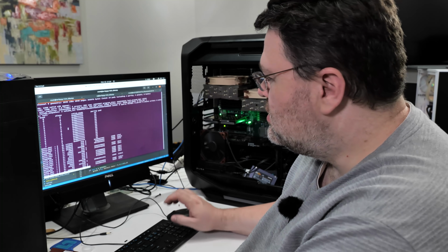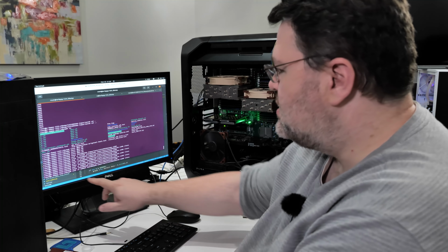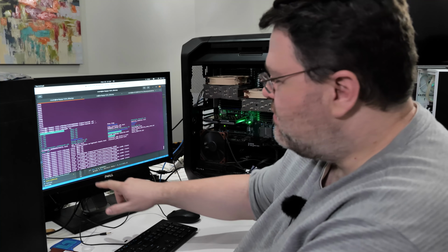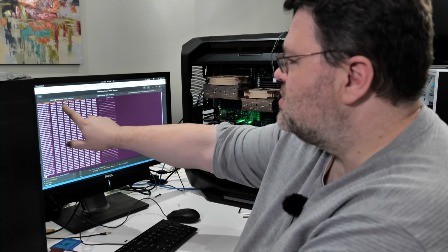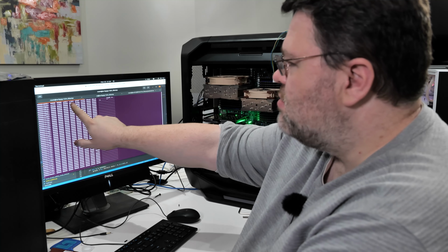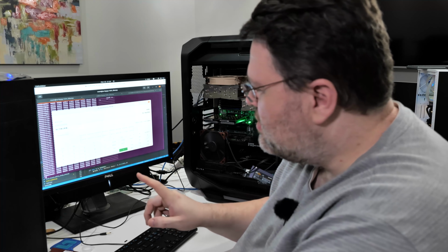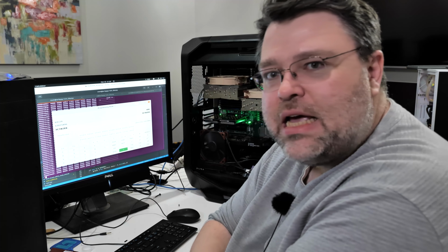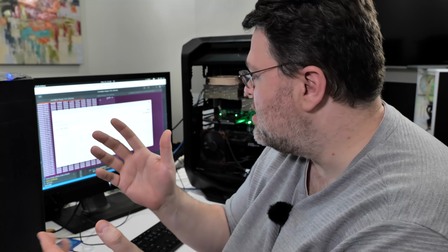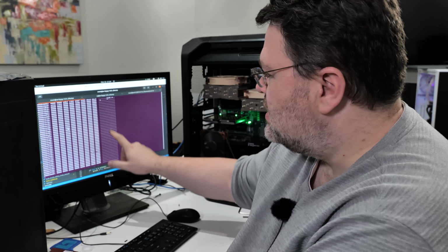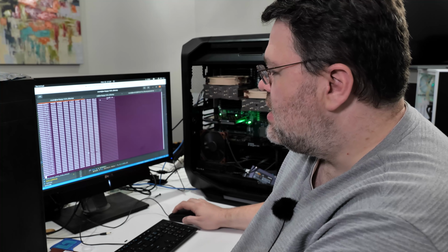3C1B2E8. So if I use XXD and skip to that offset from that file, in our EB dump, we see 9000 EB8B2C103. It's like, wait, that sounds familiar. That's our offset in Little Endian. And that makes sense it's Little Endian because it's gonna be running from the FPGA. And what follows, the next 512 bytes, in fact, is our sector.